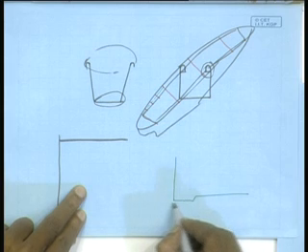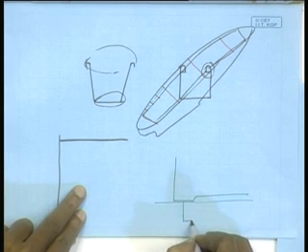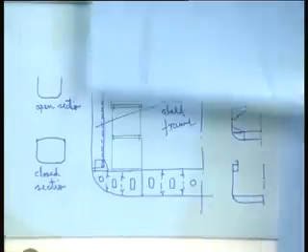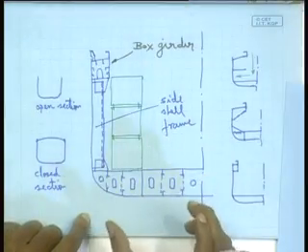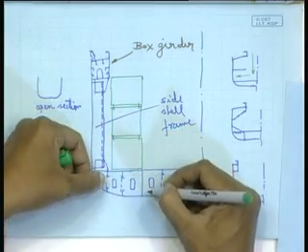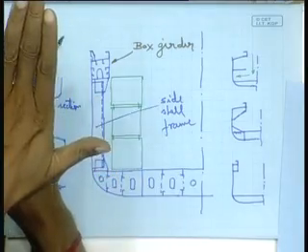It should sit on the deck, and there should be a stiffener there. The arrangement should be done keeping that in mind, that there should be a proper load path, that means it should sit on some stiffener below. Okay.